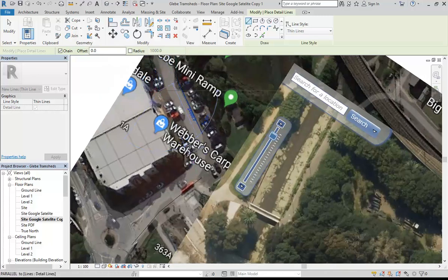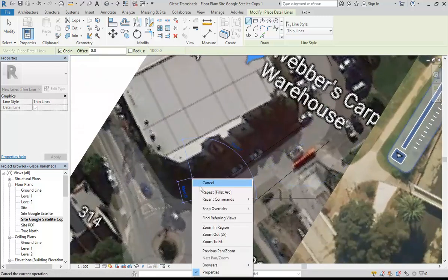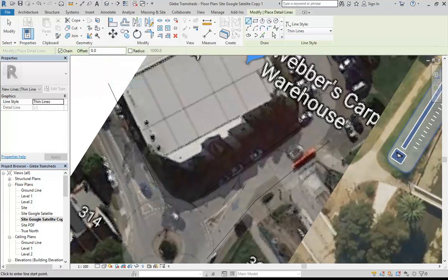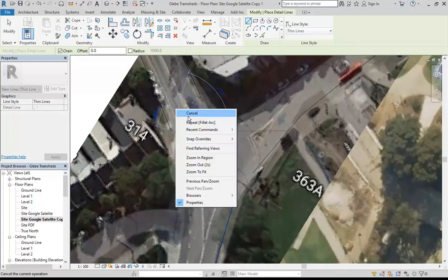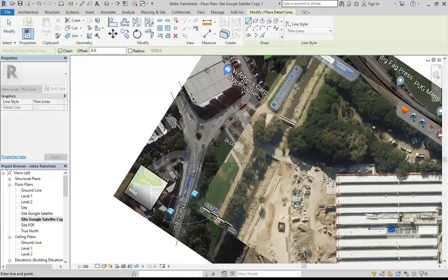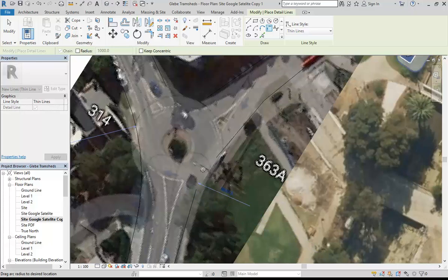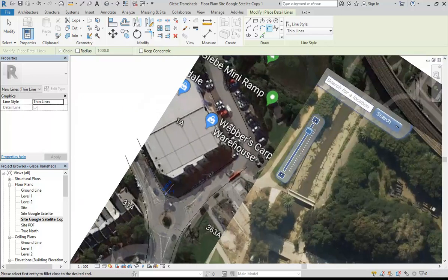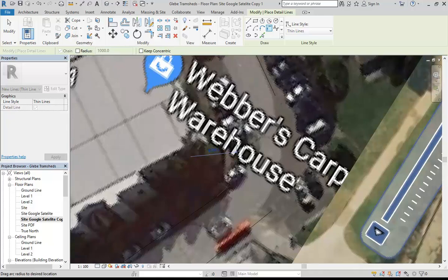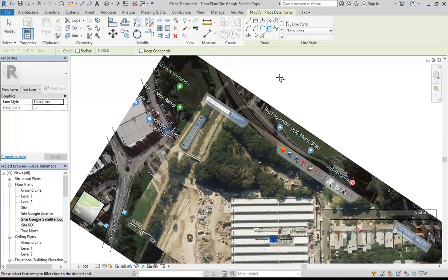And then you might have found that in Revit it seems like there's no fillet, but of course, like I just showed you, it's there, but it's in the draw panel. If you didn't know that one, that's a good thing. And so again, just very quickly tracing. So again, fillet arc, and we can join these lines together. Just get a few curves. Okay, so that's the pattern of the streets that I want to start with.